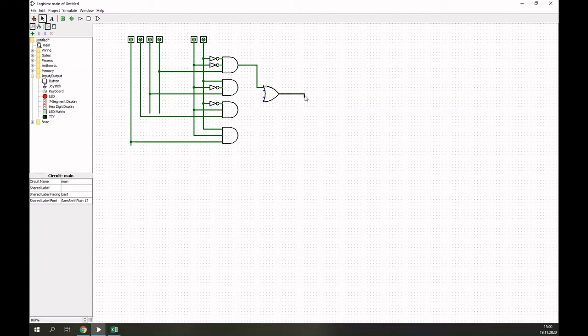So this is our output line, our single output line, which I just represent with an output pin. So this and this and this. So, and now with 0, 0, I select this pin, so I can test it. So if I switch this, it arrives in the output. I can switch the others, which will not have any effect. So if I switch this on, this will not appear, but this will appear at the output.